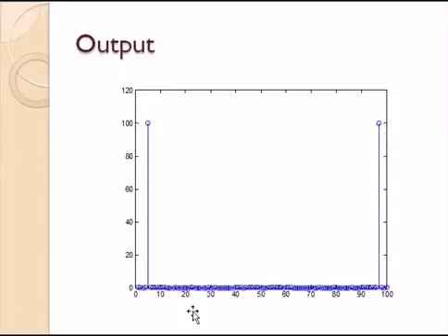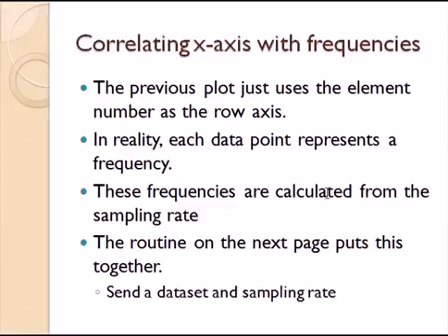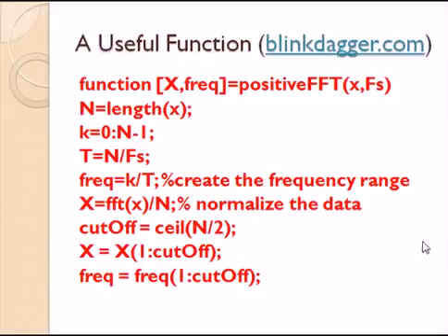But notice the x-axis here goes from 0 to 100 because I used roughly 100 samples. So it's just plotting versus the sample number. And we don't really want that. We want frequency down here so we can line up these at plus or minus 4 hertz. Now there's a variety of ways to do that. I've chosen to download a routine that does it automatically, okay? But basically, it comes out of the sample rate or the period between samples, and from that you can calculate the frequency. I prefer to use a routine that does this automatically.